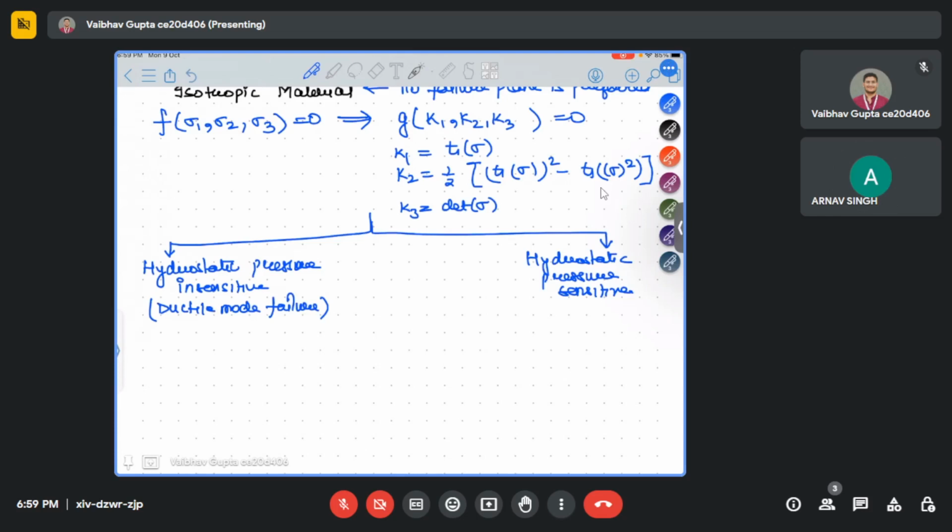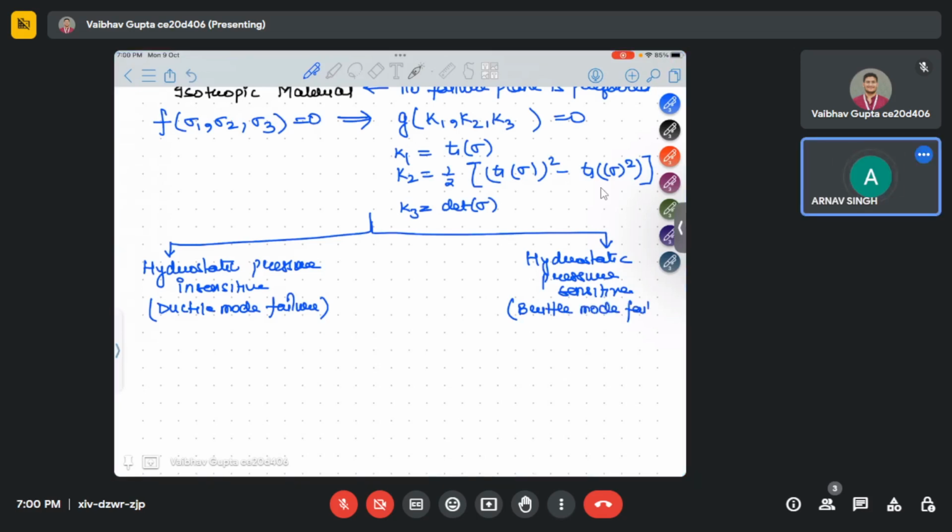So what is the steel? Steel will elongate. It won't crack suddenly. It will elongate to a certain point and then at one point it will crack. Whereas glass, if you throw it, will crack suddenly. It will break suddenly. So that sudden breaking or sudden failure is known as brittle mode of failure. And delaying of that sudden failure by exceeding its limit, by elongating the steel bar after exceeding the load, is known as ductile mode of failure.